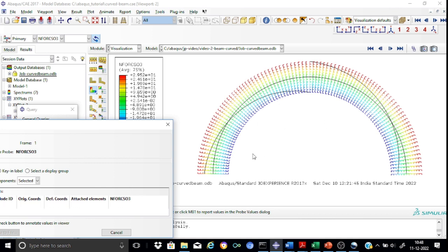Okay, fine. So that's all about the variation of the shear, and please remember that the applied load here is basically a linear load. The way in which the shear force diagram, the bending moment diagram and the torsional moment diagram all vary, these are all functions of the trigonometric variables, the sin theta, cos theta, etc. So accordingly, you have to review the results very carefully. So this is all regarding the variation of the shear force.